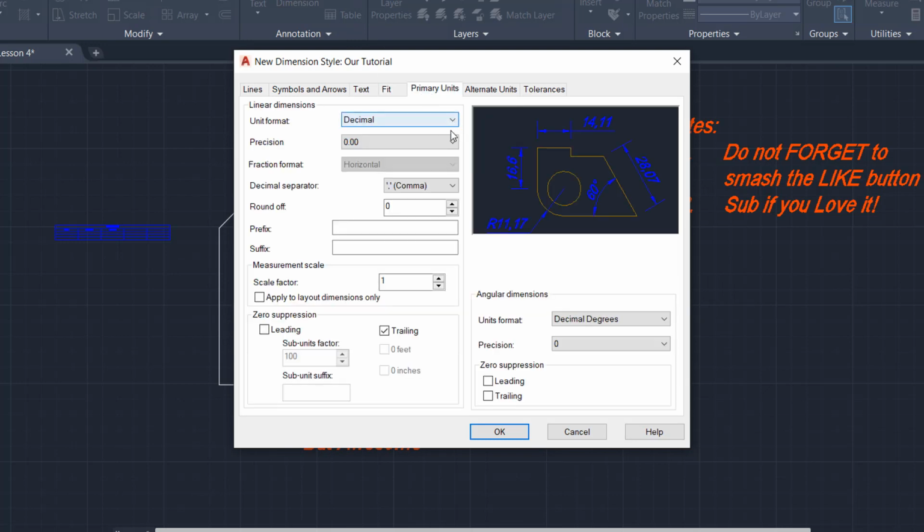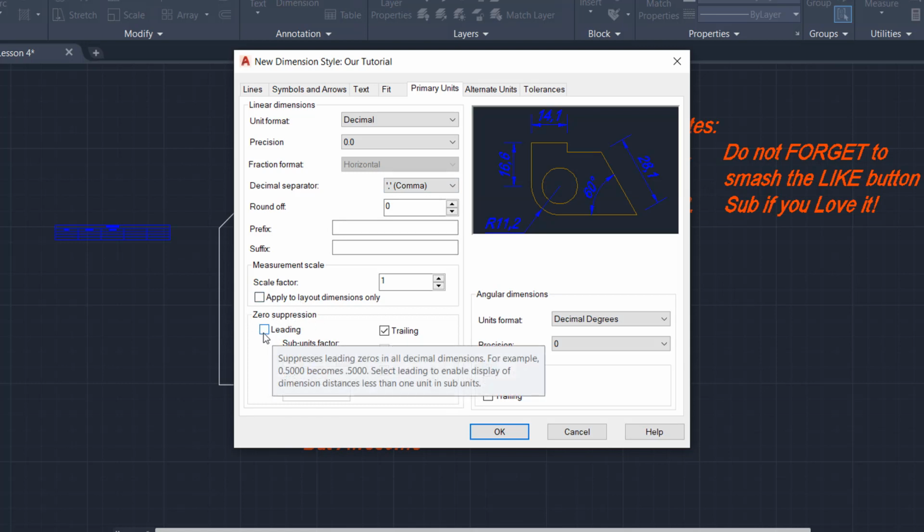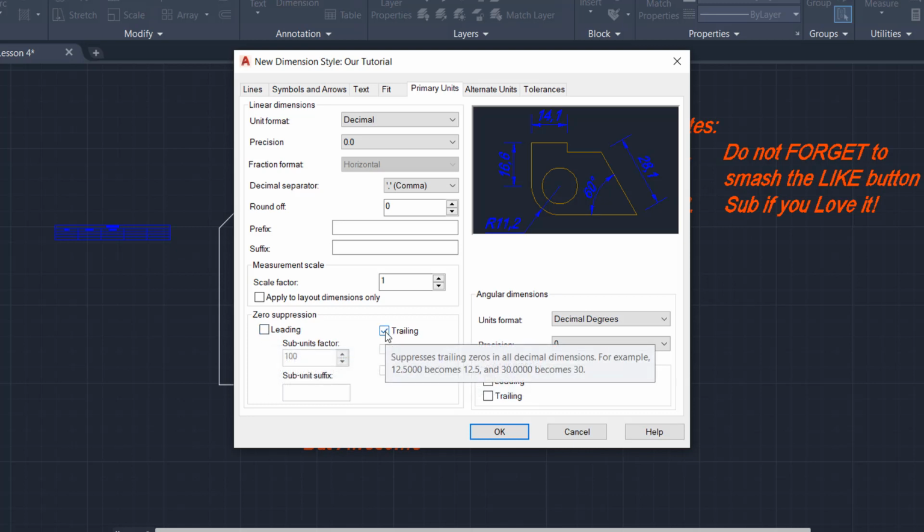Primary units will override any unit setting I may have with my dimensions. Unit format will be decimal. Precision, make it with only one decimal. Decimal separator, in some places it's comma, in others it's period. Zero suppression, as the name suggests, remove zeros in the decimal to make it clean. Leading is for zeros on the left before separator, trailing is for zeros on the right after the separator. This one here is for angular dimension, same as in linear dimensions.